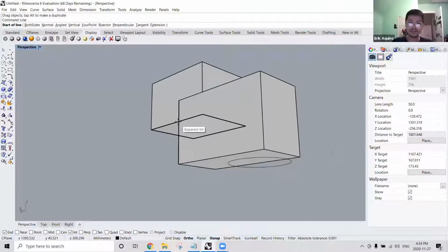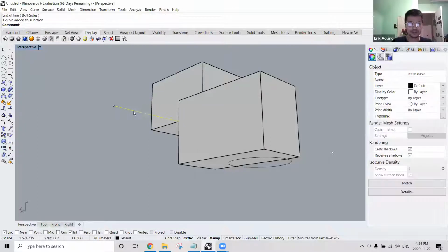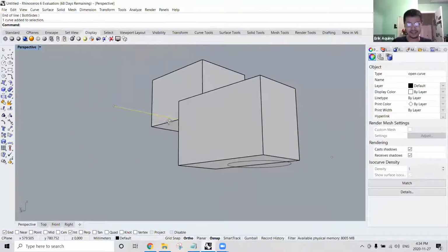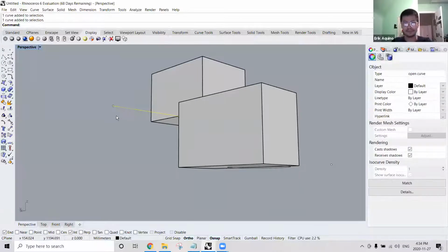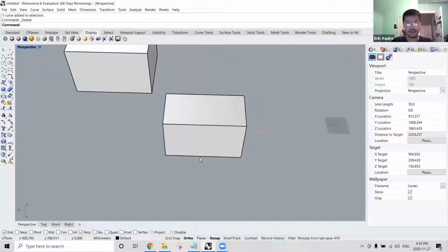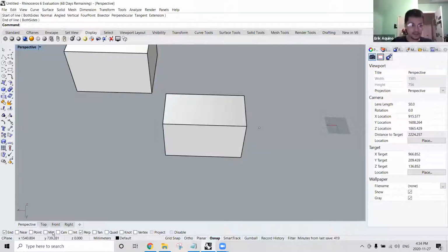And I want you to be aware of that, because if you end up trying to create your geometry in your building with an apparent intersection, you're going to find that that's not really useful. And lastly, I'll just talk about perpendicular, which is if I'm creating a line, for example, starting at any point, I can make it perpendicular to an edge or a surface. So in this case, it's perpendicular to a rectangle here. So those are mainly the ones you'll be using, and I don't want to have to go over this for the moment.